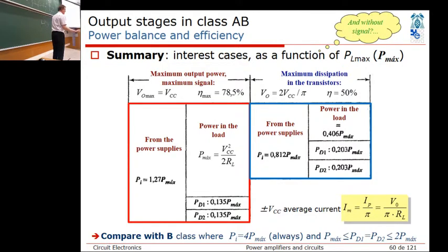What happens there? That's the distortion. What happens on heavy metal? Because Jimi Hendrix overdrove the amplifier, so that you actually get clipping distortion. Meaning, okay, you try to drive it like that, but your power supply is like this.